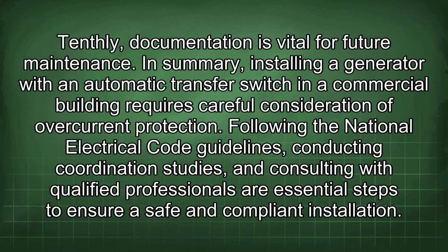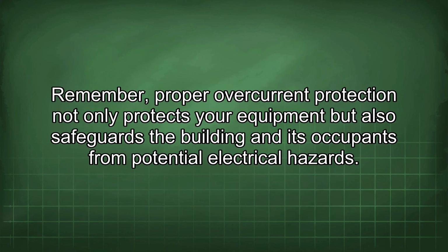In summary, installing a generator with an automatic transfer switch in a commercial building requires careful consideration of overcurrent protection. Following the National Electrical Code guidelines, conducting coordination studies, and consulting with qualified professionals are essential steps to ensure a safe and compliant installation. Remember, proper overcurrent protection not only protects your equipment, but also safeguards the building and its occupants from potential electrical hazards.